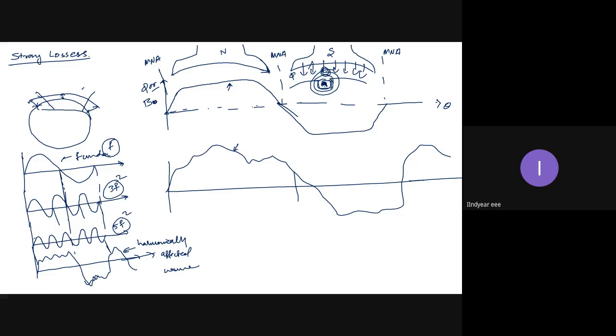So that flux, which is a leakage flux completing its own path around the conductor, is linking this conductor again. And please remember, the current flowing in the armature conductor is AC, alternating. Therefore, the EMF is induced in this conductor. The flux created by the conductor is linking the same conductor. Therefore, EMF is induced in the conductor. It is not back EMF. Please remember this.